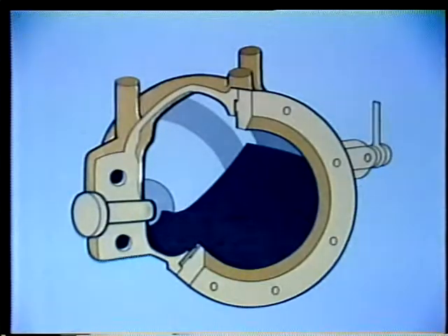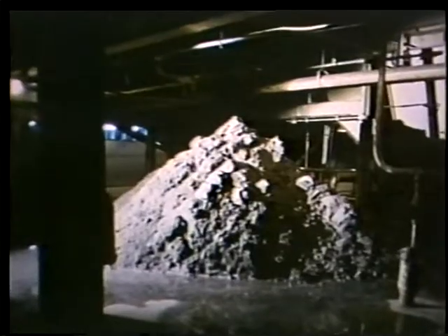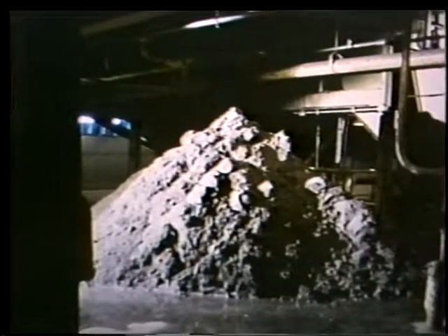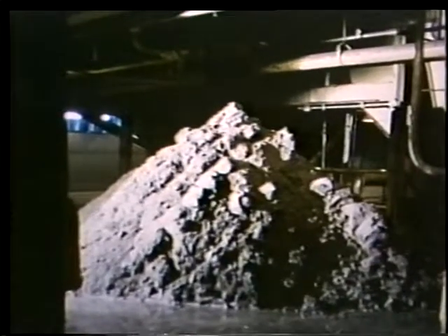Well, this is a common ball valve, a type of basic valve we talked about earlier. A special variation of it is the V-ball valve. The V-ball valve is finding wider use because, like the pinch valve, it has very low pressure drop characteristics and does not slow down flow through it. It also is resistant to clogging, which makes it adaptable to a wide variety of flow materials. For example, slurries such as pulp, coal, or ash can be controlled through the V-ball valve.